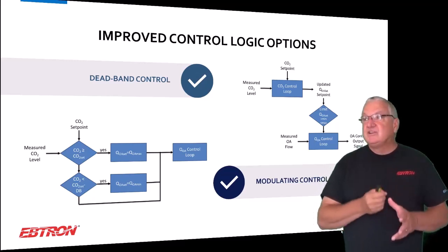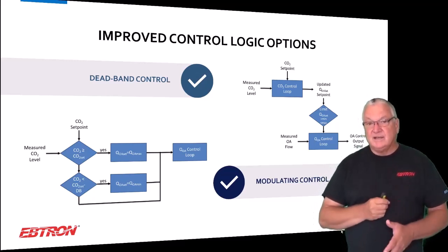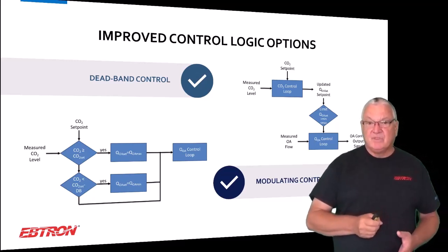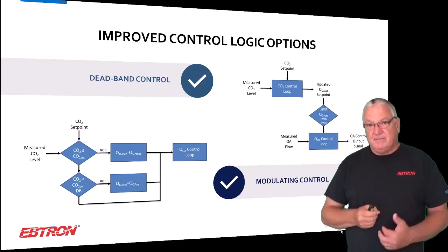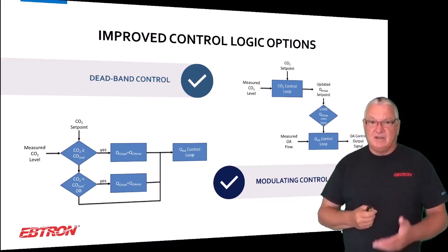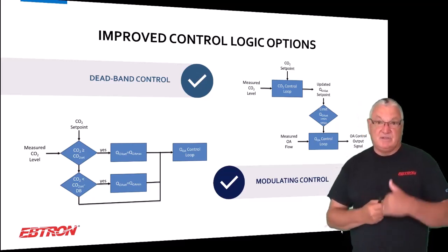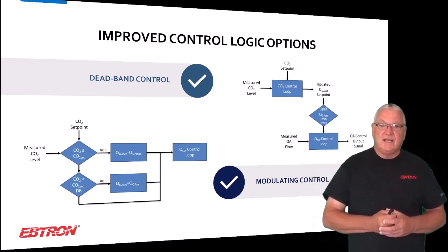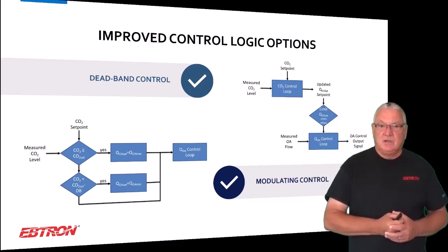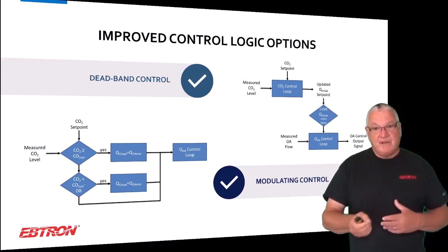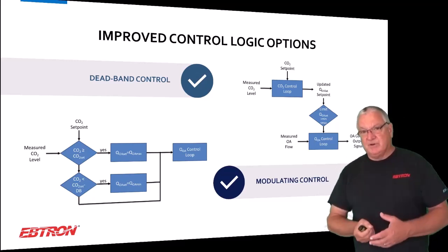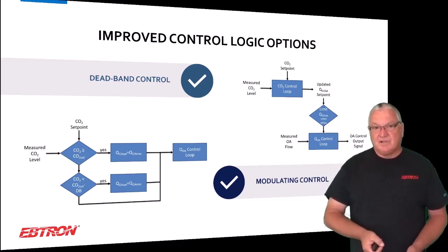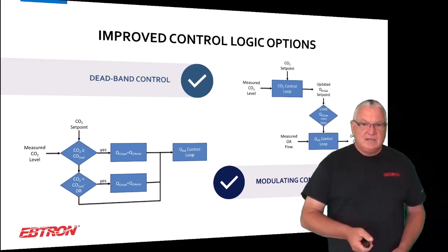It's going to go into a control loop or just a simple reset loop that outputs an airflow set point. It's going to compare it to the min and max. If it's under the min, it's going to set it to the min. If it's over the max, it's going to set it to max. In between, it's in between. And that set point goes into an outside air control loop where you measure the outside air, and then the output of that is either something as simple as modulating a damper or a more complex sequence, okay?